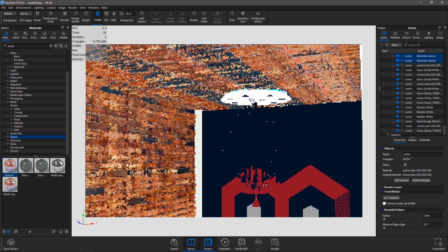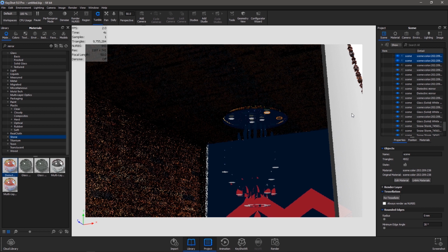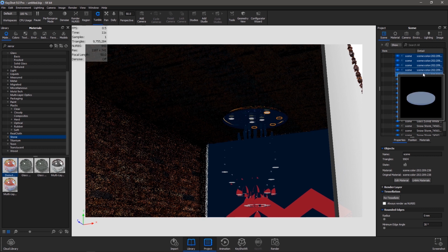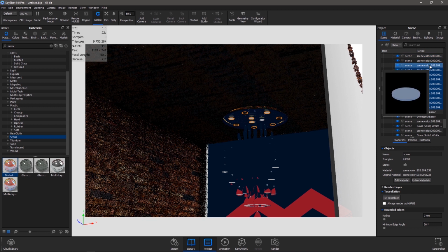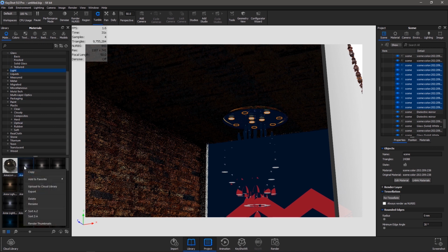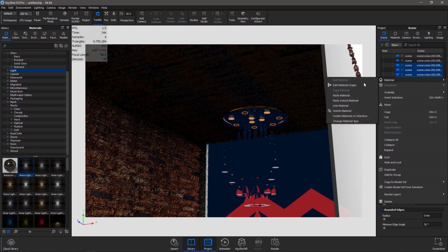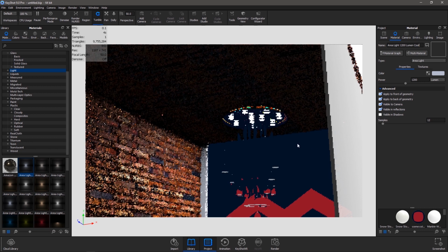Okay, it's applied. Now the time for the light sources. You can see they are visible now. Just hit and try. Okay, we have the external lights. Now select the internal lights. So all the lights are selected. Okay, remove the mirror, go to the lights. Select this area light, the first one. Just paste it here. Paste material. Go for edit. And everything is fine. Just zoom out.